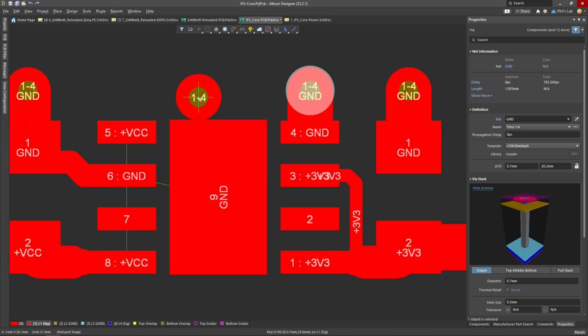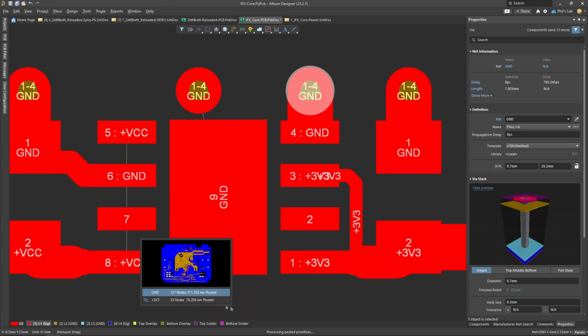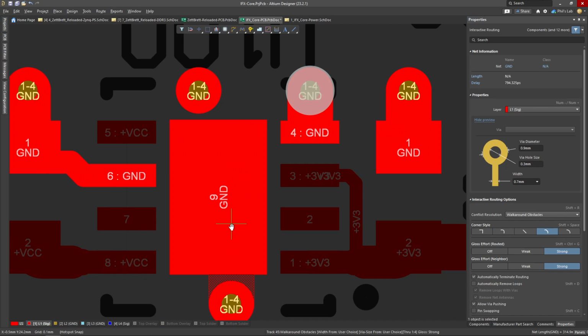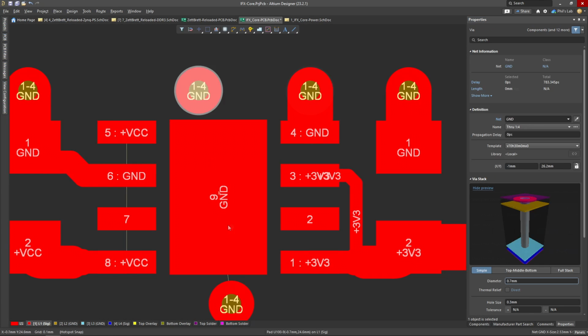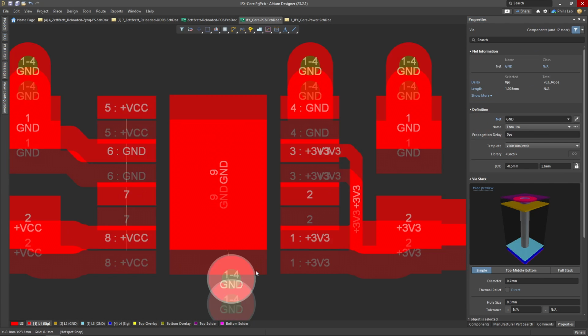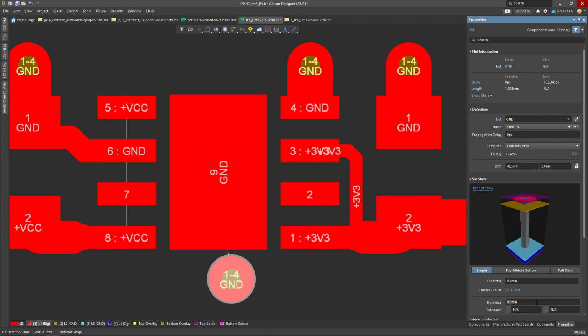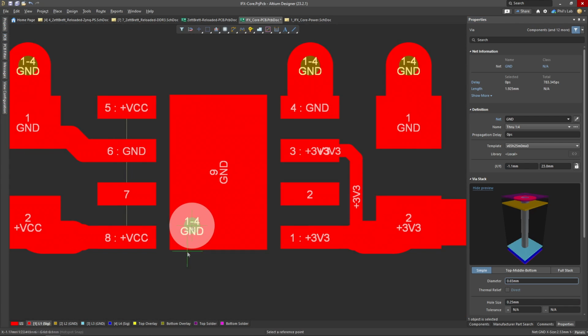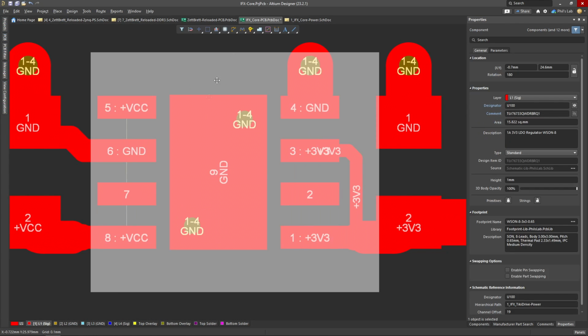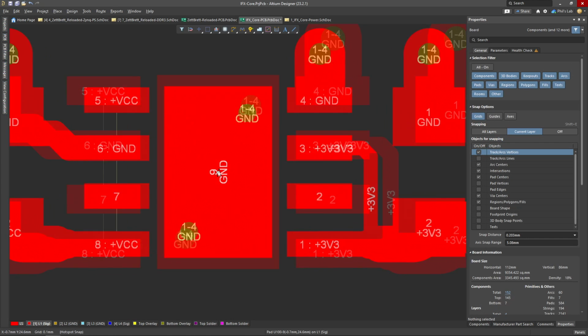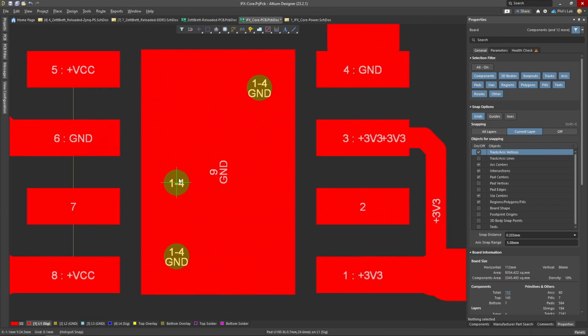I could place thermal vias, for example, like here and like here, and then have wide traces going in, but that increases the thermal resistance of my connections. A compromise then is, and we need to do this without adding too much cost to our PCB, by reducing the hole size. So typically I would go, for example, for a 0.25mm drill, maybe a slightly smaller pad, and then place that closer to the outsides and place them, for example, like so. Of course, I can place more vias, but that will increase the chance of solder being wicked away. So I try to avoid placing them directly in the center, maybe more of the outskirts.